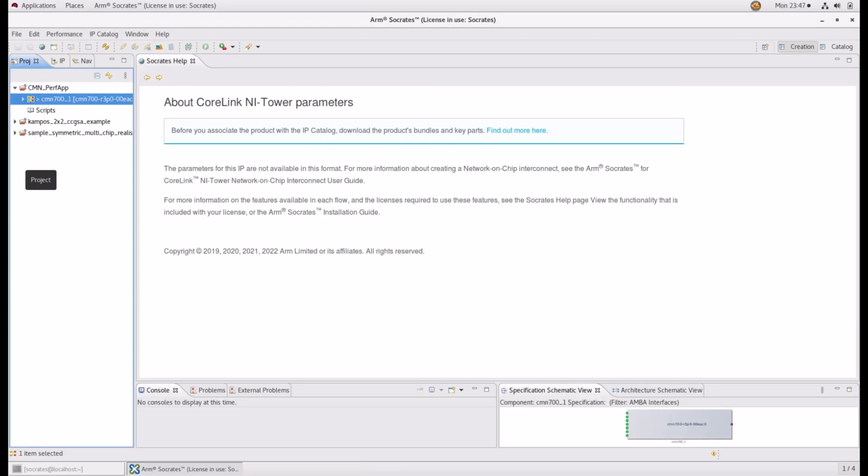You can run simulations of CMN-700 using a dynamic model that matches your configuration to evaluate the performance of your CMN-700 and potentially drive the architecture refinements. The latest version of the CMN-700 Performance Flow enables you to configure and run two different types of performance data configuration setups. This allows you to investigate the expected performance of CMN-700 configurations. The two modes of performance configurations for CMN-700 are single CMN-700 mesh mode and multi-CMN-700 mesh with coherent multi-chip link mode.